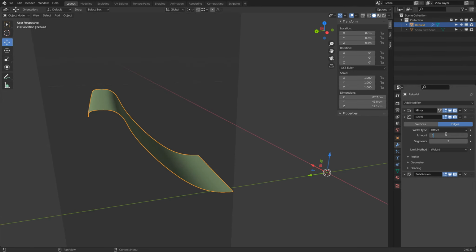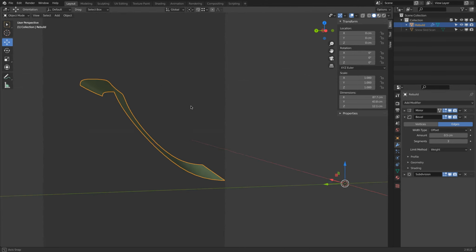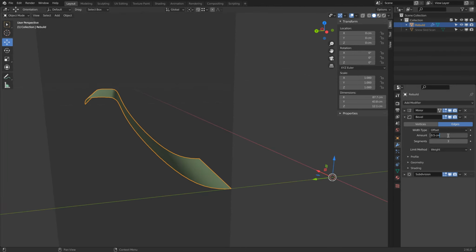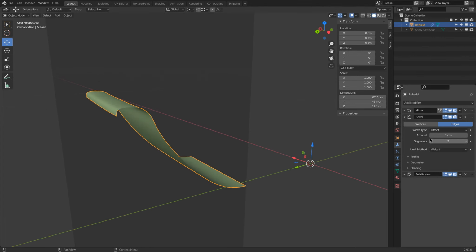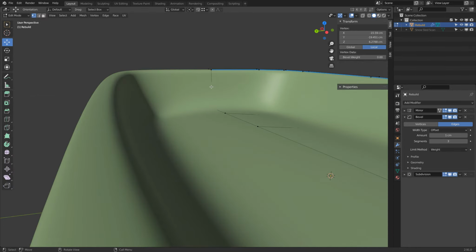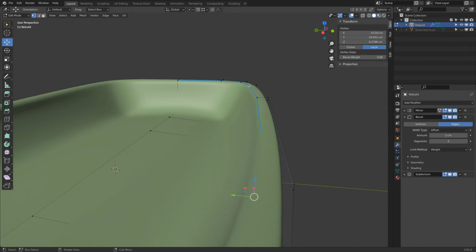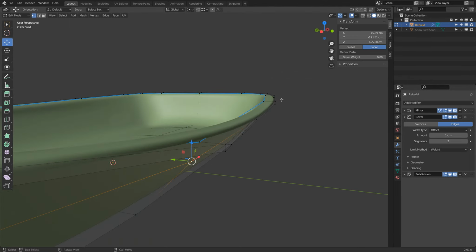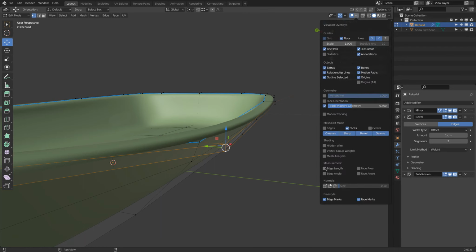What about 0.5 centimeters? So 1 centimeter. Let's go with 1 centimeter. This might be easier for the moment. And here's now an interesting trick when we go to edit mode. So this inner area we have filleted, and this outer edge I selected via Alt left mouse button click. We want to fillet too, but we know this has a distance of, what was it, half a centimeter?